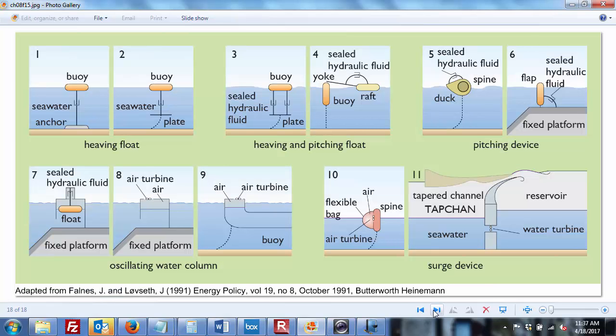Okay, so now, just as we did with the wind chapter, we're seeing a lot of different types of wave turbines. Some of them, again, here's just your up and down. In the case of these buoys, you can also seal it, so you've got some kind of hydraulic fluid being pumped back and forth. In this case, the raft is keeping this guy stationary as it moves back and forth, supplying energy. Every one of them is tethered in some way, if you're actually going to tap this and grid tie it rather than just running something offshore.